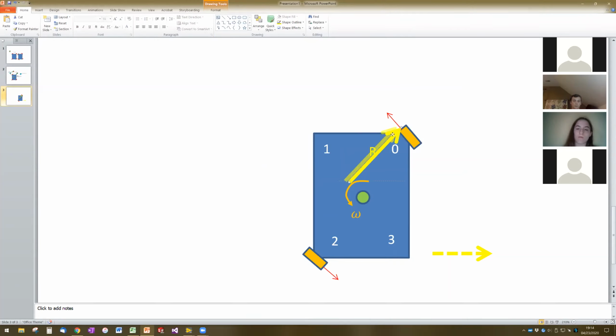So the key concept, which we got intuitively originally, is that when we turn the wheels like this, the radius out to them is perpendicular to the velocity vector. So all of your radius and all of your velocity are being used to rotate the robot.